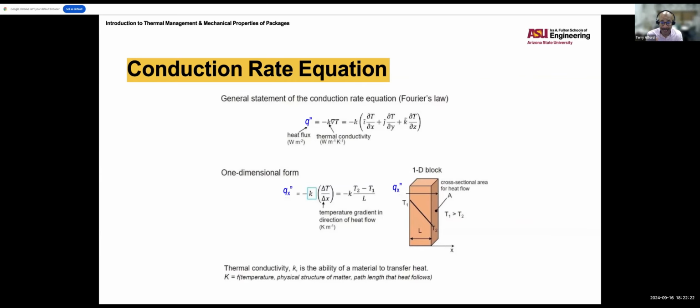For example, pure silver, 1.67 micro ohm centimeters. Copper comes in about 1.7. Okay? Aluminum, 2.27. Gold, I think it's 2.9. Okay, good electrical conductors. Well, we have the same thing we will see in thermal conductivity.